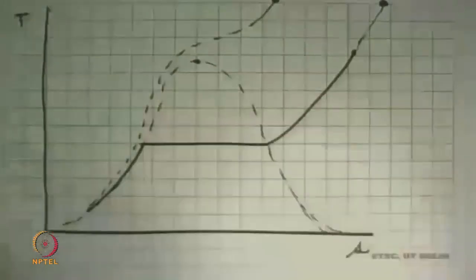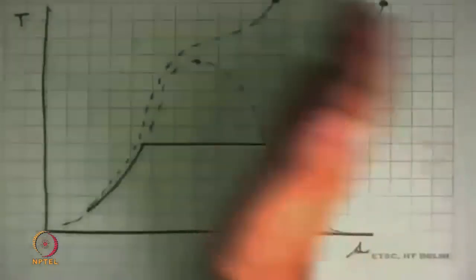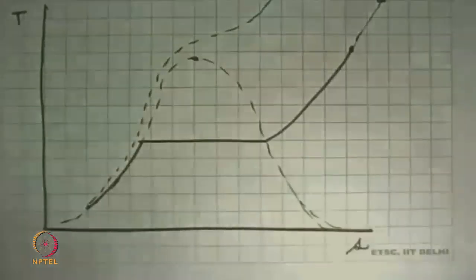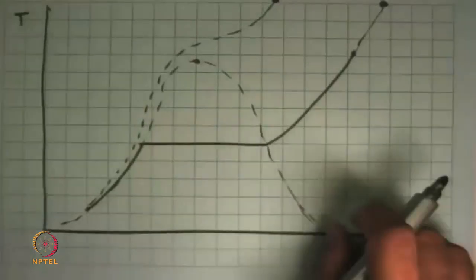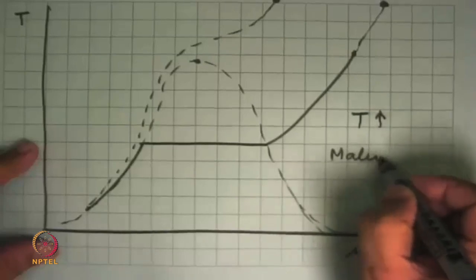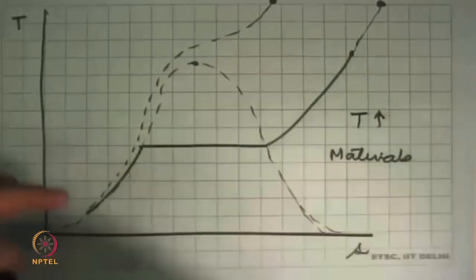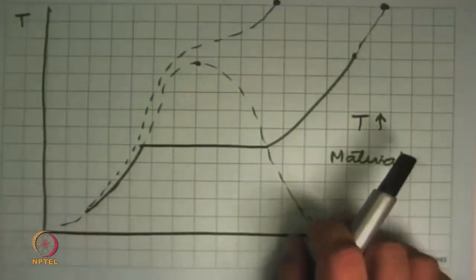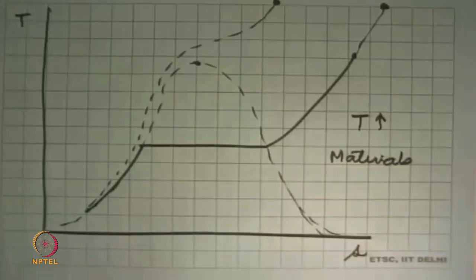So that is the reason why traditionally pressures have gone up, temperatures have gone up, and we are coming to supercritical pressures and temperatures. The limiting factor though, thermodynamics tells you that you can go as high as you want in temperature, but we do not have materials for making a boiler that can withstand such high temperatures at high pressures for 20-30 years. That's the challenge. Okay, so with that we will conclude this session. Tomorrow we'll look at some more of the property diagrams, take some more examples, and then we will go on to see what is ideal gas behavior.